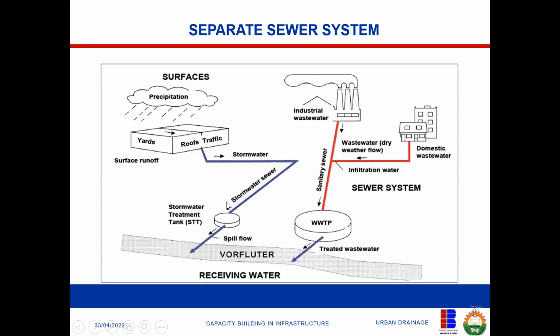This thing is not usually available, but this is for developed countries. They will have what they call a stormwater treatment tank. It's not like they are putting any chemical here. When the water falls here, the top one will overflow. The highly turbid sludge at the bottom will be evacuated either by hand or through another pipe, or taken and dried on the surface.